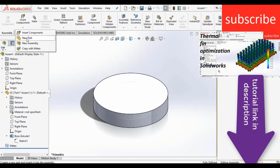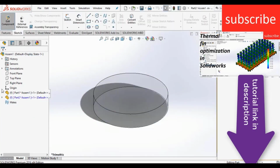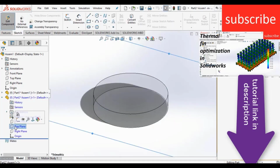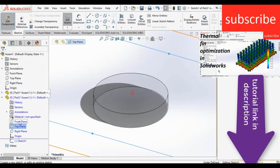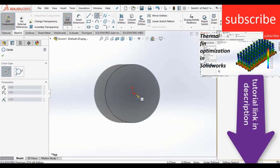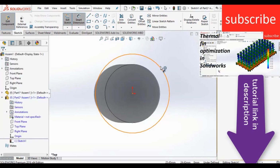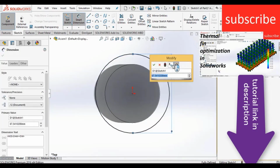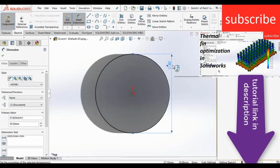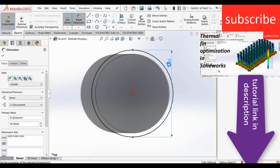Now click here, click on new part, select the new part, and click on edit component. Now select the top plane, click on sketch, and press Ctrl+8 for a normal-to view. Now here I am making the heat sink of my chip. So enter the diameter. You can increase or decrease the diameter as per your requirement. So let's say 55 mm diameter.